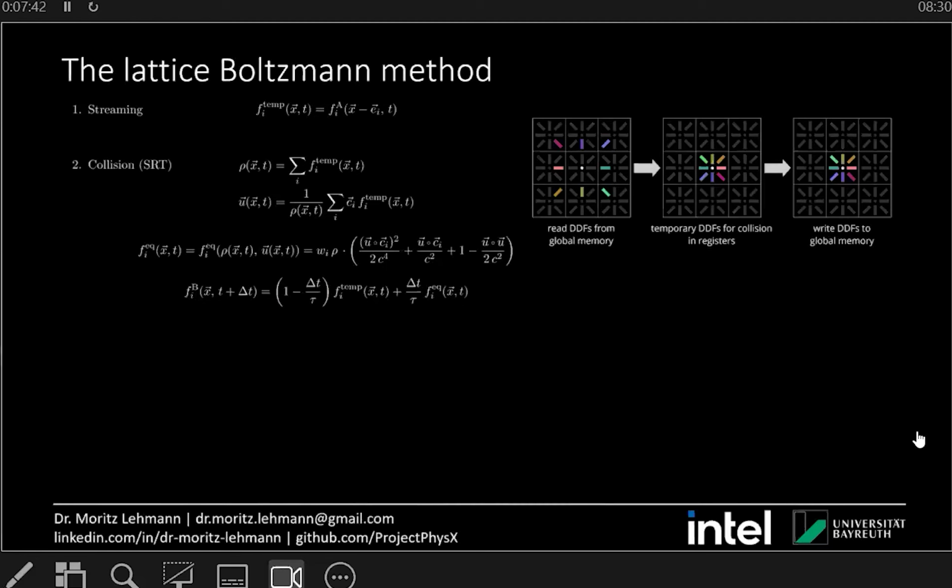And the first thing to introduce is that Lattice-Boltzmann consists of these so-called density distribution functions. And they're visualized here as these color bars on the grid. So each grid cell has, in 2 dimensions, 9 density distribution functions. One, that's a dot in the middle, and then left, right, top, bottom, and the diagonals.